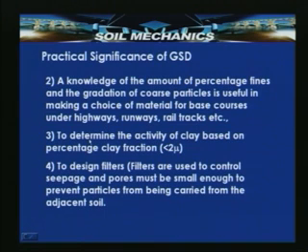And another practical significance, which we will be discussing later, is to determine the activity of the clay based on the percentage of the clay fraction. That means based on the percentage clay fraction, we can say whether that particular clay soil, with particles finer than 2 micron, is active or inactive, or to what extent it is active. All these things can be said by determining the activity, which is possible with the percentage clay fraction.